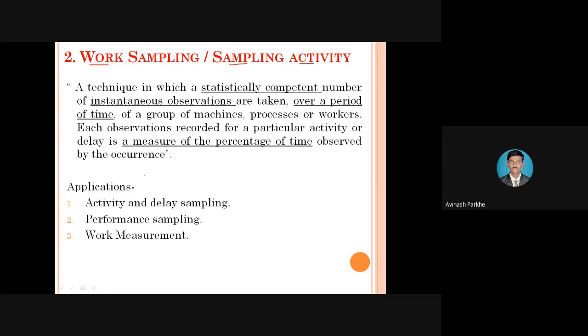You know about sampling operations. A lot of products are available, and from that number of products, we have to choose one product and go for the measurement. Sampling is one of the activities performed in industry. That is, 100 products are available, and from those 100 products, you take 5 products and measure the dimensions. If all the dimensions are as per the requirement and it is satisfied, then the total 100 products are selected for further process.